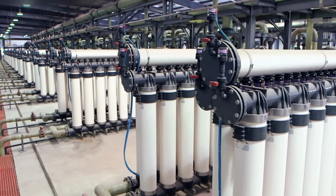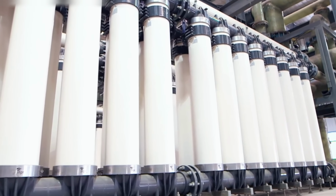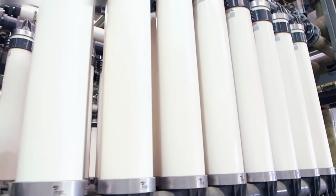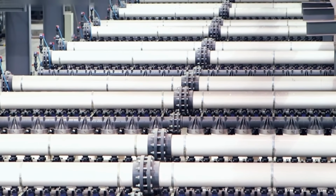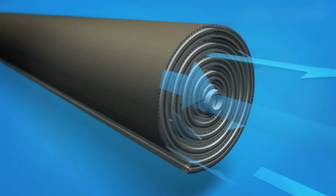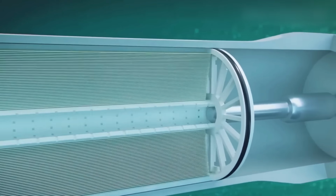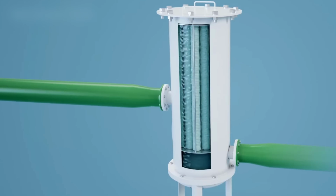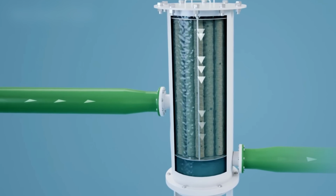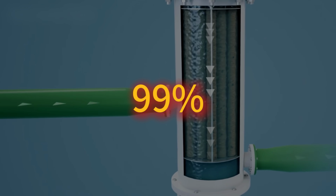Inside each pressure vessel are several cylindrical membrane elements. Instead of using one flat sheet, layers of membrane and flow channels are wound around a central collection tube. This creates a large membrane surface area inside a relatively compact cylinder. Pressurized seawater flows along one side of this membrane. Water passes through the membrane and moves toward the collection tube, while the vast majority of dissolved salts remain behind. Modern seawater RO membranes can reject more than 99% of many dissolved salts.